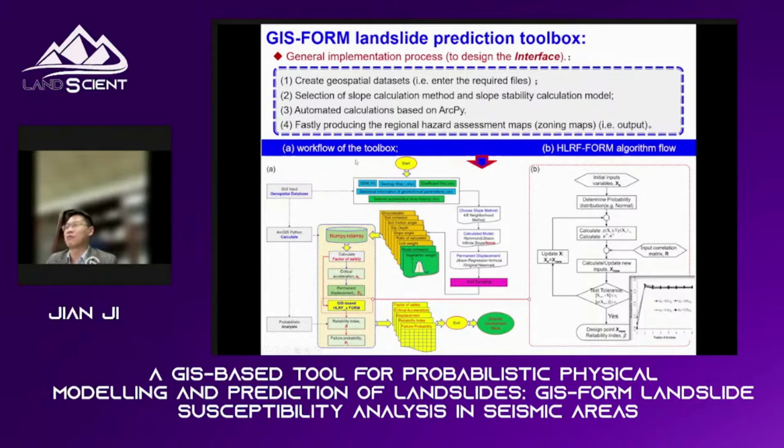the toolbox, how we developed our toolbox and the workflow, including the inputs: the original DEM information, the geological map, soil coefficients, and some statistical information of the geotechnical parameters. We also use the NumPy package integrated with ArcGIS.